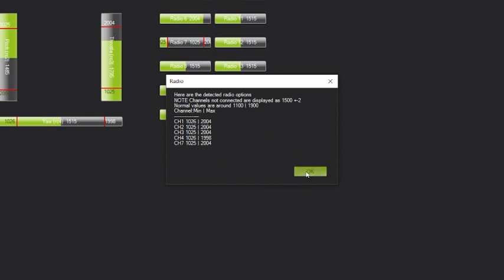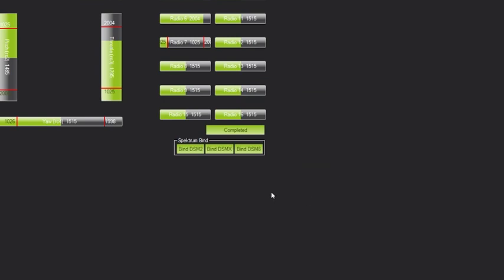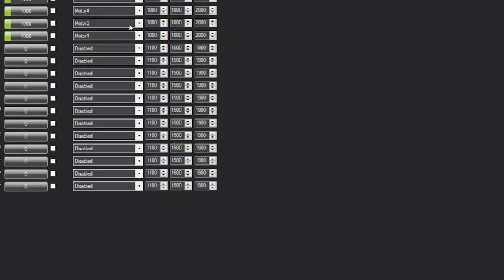And there it goes. It shows us all of those values that it was able to calculate. And we say okay. And once you add your channel 7, you'll need to go back and redo this, as hopefully you've already changed these to show the same functions as I'm showing. Otherwise, what this is pretty much verifying for us is that we want to make sure that not only is the quadcopter, the flight controller, spinning the right motors that we want it to and that it thinks it is, but also that our motors are spinning in the right direction.